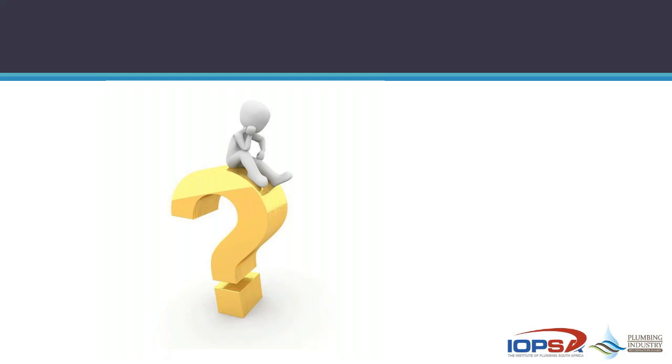So at 40 liters per person per year, if you have got 5 people, that means that every year that thing is in use, you'll have 200 liters of sludge down the bottom. So yes, if you only have a 500-liter tank or you have a 1,500-liter tank, you'll have to get one of those vacuum tankers to come and empty that thing, and it'll start working from scratch again.